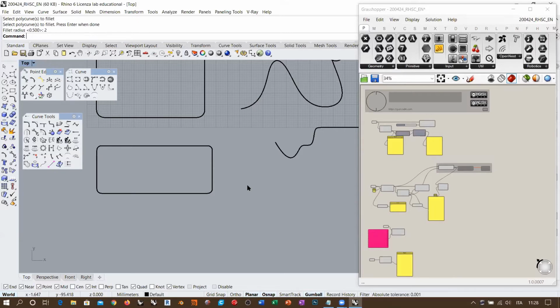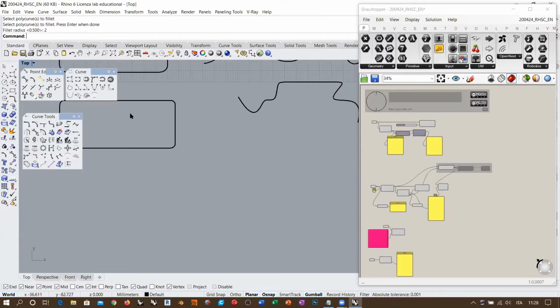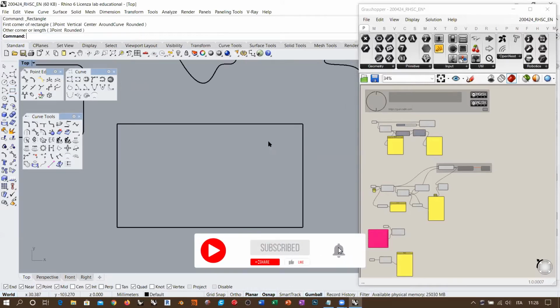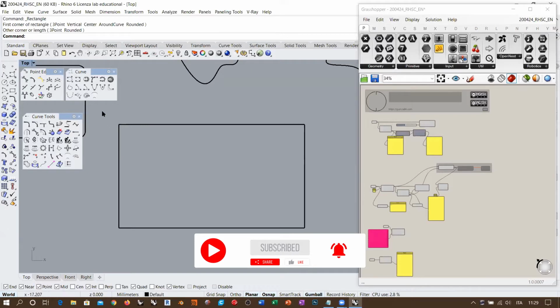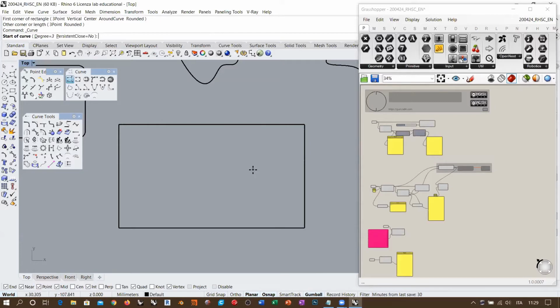But there is another option now, and this option is, well, depending on the type of result that you want to achieve, but this option gives us a totally new look at this kind of problem. So I could create, for example, a NURBS curve using this rectangle as a reference. Like this, for example. I will create a starting point here and another point here, and I need 4 points in a row to have a straight segment along this side. So I need to place 1 point here and another point here. So I'm moving in this counterclockwise direction.